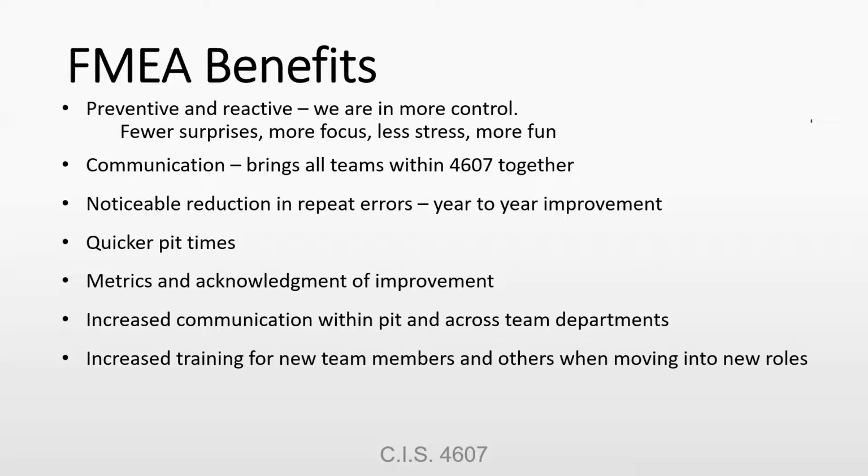With it, we increase our training because we know what we're having problems with, so we train someone in it. Like Loctite, we created that from FMEA because we realized that there was a problem and that people needed to know how to use it and weren't just using it without knowing how. We've actually Loctited movable parts before.